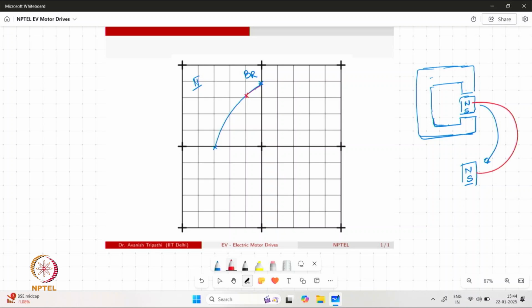And if you try to keep it back again into that closed path, we find, and it's another observation for magnets, that it never goes back to the same value of Br, but rather takes a different path and has a little lower value of this remnant magnetic field. And every time we repeat this process, it takes a small contour about that new axis, which is called the recoil axis for the magnet.